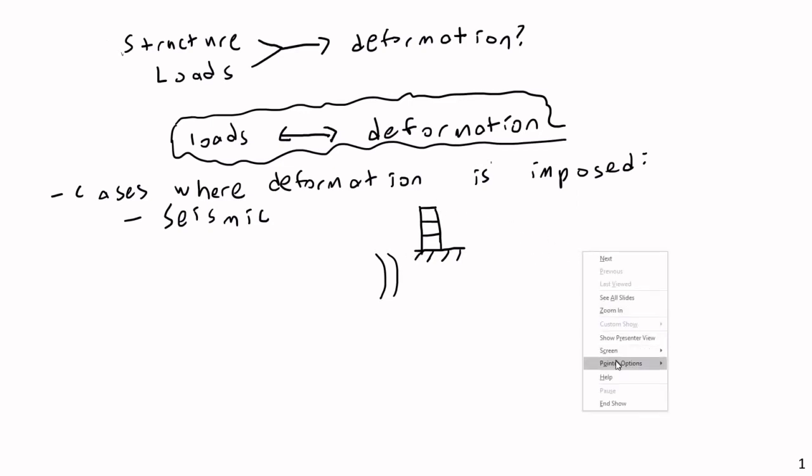And so when the foundation of your building basically just moves out from beneath it, what ends up happening is it passes by relatively quickly, and so suddenly your foundation is basically no longer underneath where your building is. So the ground moves to the right here as the seismic wave passes by, and the foundation actually moves to the right here, and the rest of the building hasn't caught up yet. So the building's foundation jolts over to the right, and the rest of the building is still hanging out up here, just unsure of what's going on. And the only way that the building can move to right itself on the new location is if stresses are transferred through the members to bring this back to equilibrium.